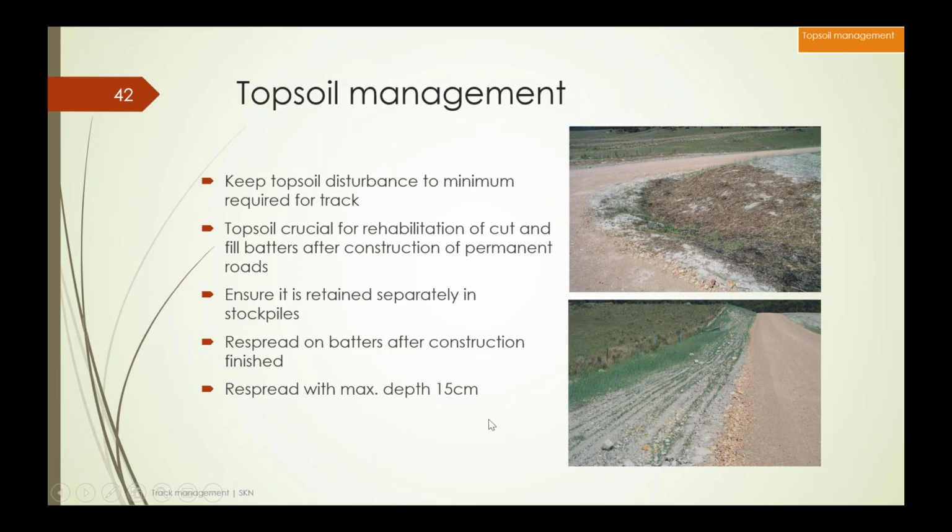So with a bit of thought, you'll be able to find a location where you can stockpile the topsoil, and then you're in a position to be able to reuse it once you've finished, rather than seeing it covered up in fill as it comes out of the cutting. So it's something to perhaps think about, actually having a formal location of where you might stockpile your topsoil, somewhere that's going to be out of the way of the main construction activities.